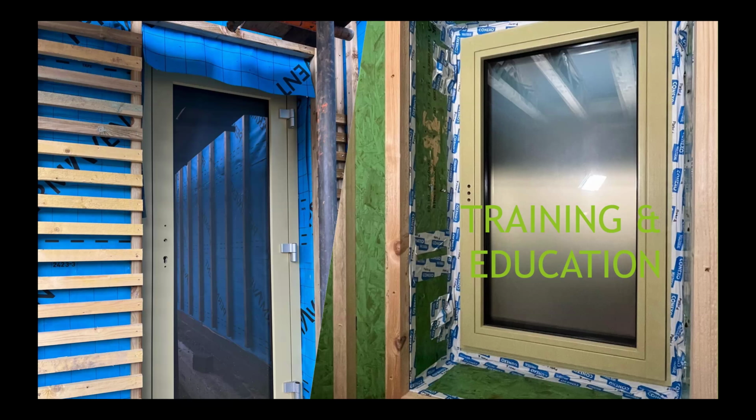And on the window details that you can see there, we've had a very senior foreman that we've parted ways with now. Very good joiner foreman on all our traditional builds. But as you can see there, and we actually had Phil Bixby on the call today, come with his infrared camera to do a little bit of snagging with us. We found that he hasn't put the insulation on the outside of the windows. It's not the end of the world because we can take the cladding off and do it that way. But all these things that we've learned have come from this one job.